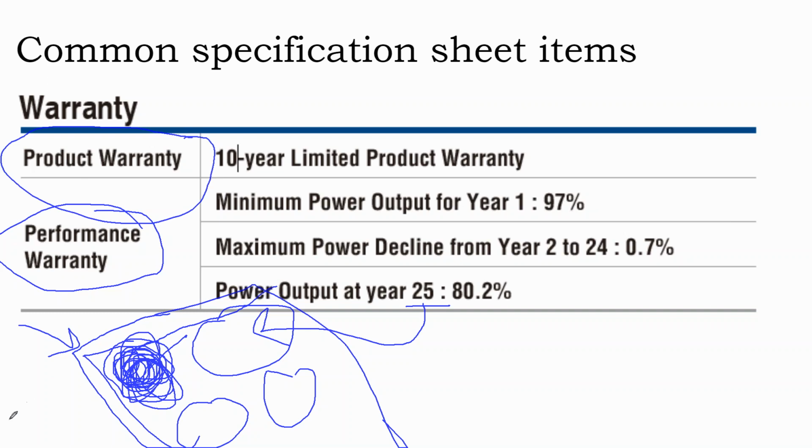The product warranty is for everything else, such as the connection point between the solar frame and the solar panel itself. And so if the solar frame falls apart and water gets into the panel and it shorts out the panel, that's not a cell issue, that's a module frame issue. And to a customer, they might say it's the same issue, but really it's not, because the manufacturer can vouch for the quality of the cells, but he can't vouch for the quality of the installation.